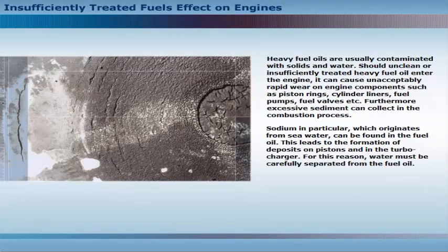Heavy fuel oils are usually contaminated with solids and water. Should unclean or insufficiently treated heavy fuel oil enter the engine, it can cause unacceptably rapid wear on engine components, such as piston rings, cylinder liners, fuel pumps, fuel valves, etc.